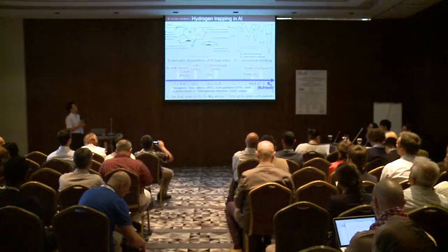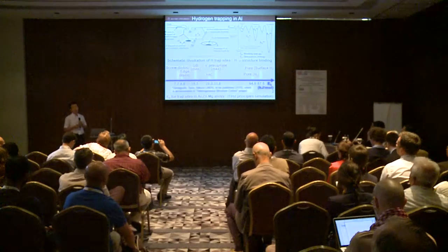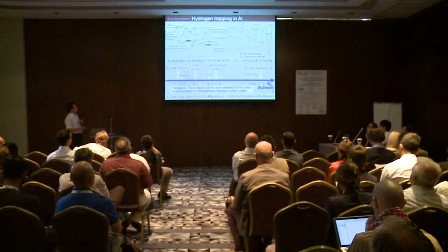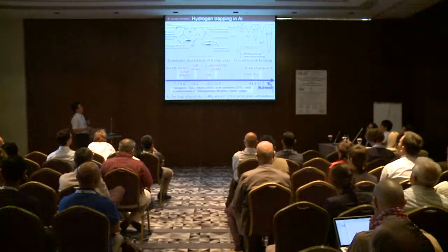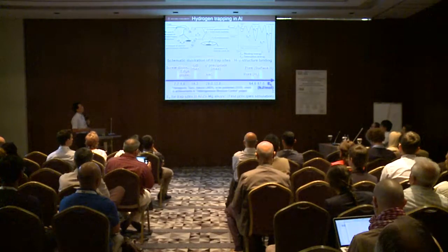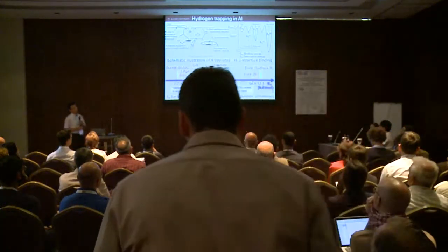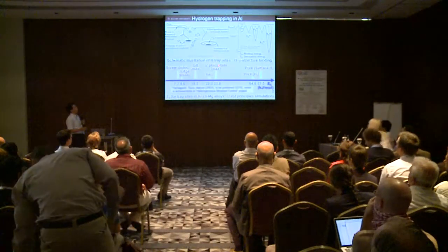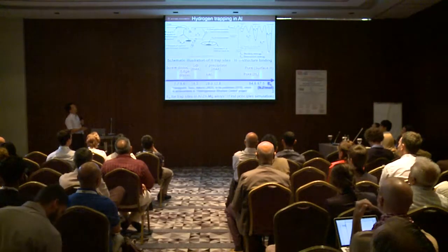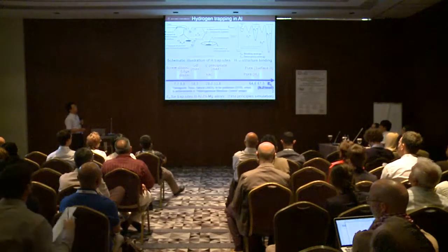As we have seen many times in this symposium, hydrogen is stored in various hydrogen trap sites, and different trap sites have different binding energies. If you take a look at this list of binding energies for various hydrogen trap sites in aluminum-zinc-magnesium alloys, you can see that both screw and edge dislocations have relatively low binding energies, and grain boundaries, precipitates, and vacancies are intermediate. Atomic hydrogen adsorbed on the aluminum surface, and hydrogen separated from aluminum as molecular hydrogen, have very high binding energies.